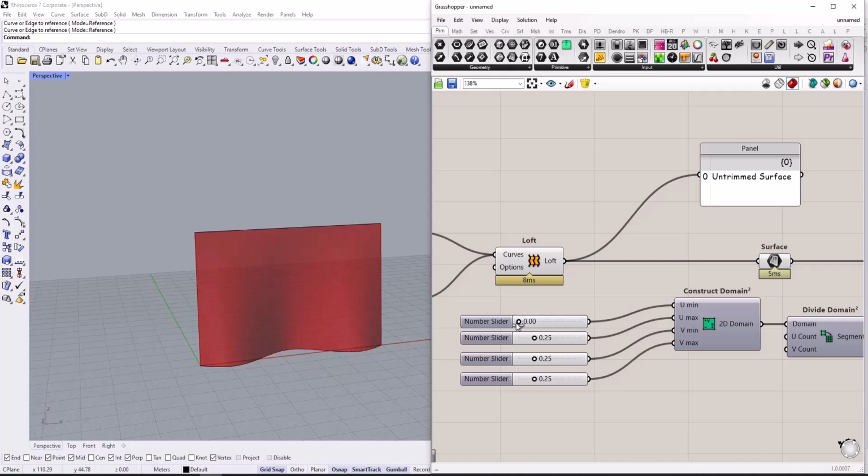For example, I set this one from 0 to 1, and for the other one, I define its range from one section to another. We do this because the exercise we are working on might not need to cover the entire surface. This way, you can easily control which areas are included. You can also experiment with different values and adjust the effect in different directions. I make them a little bit tidy again to ensure the entire surface is covered.